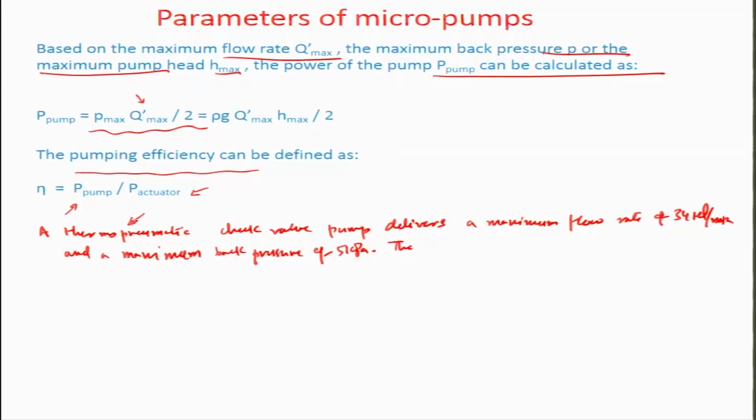We have already seen this while designing the static valve example in one of the lectures. So here we are actuating a heater with a certain resistance to go up to a certain temperature, so that it heats up a hermetically sealed cylinder with, let us say, an air confinement, and the air expands because of Charles's law and creates a membrane deflection.